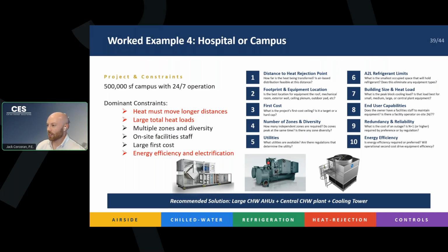And your cooling tower sits outside. You don't have to have that sitting in your room. That can sit outside on the roof or on grade, wherever it makes sense for you. But those cooling towers are dense, right? You can have a lot of tonnage in a small footprint, which is one of their powerful pros that you can use.